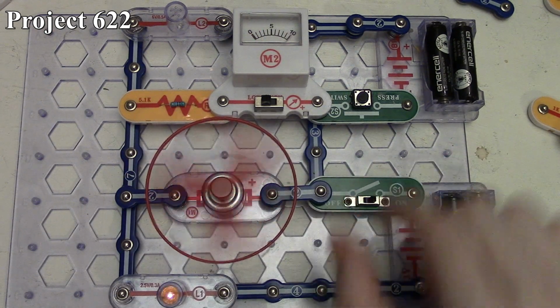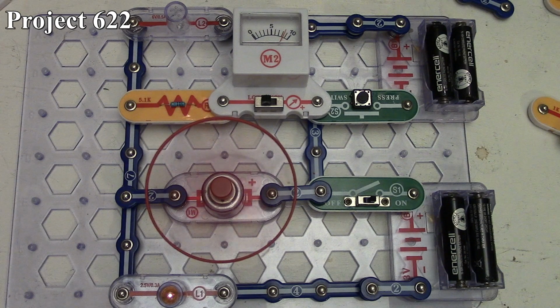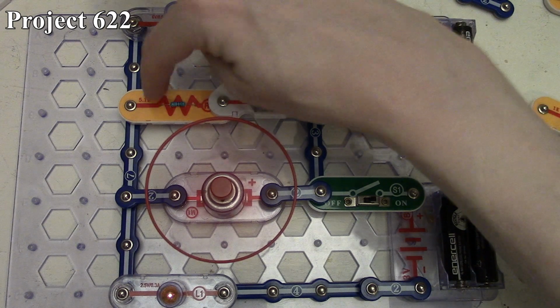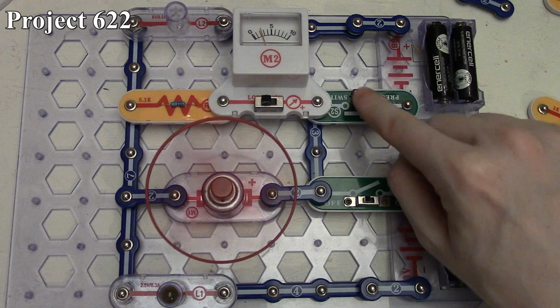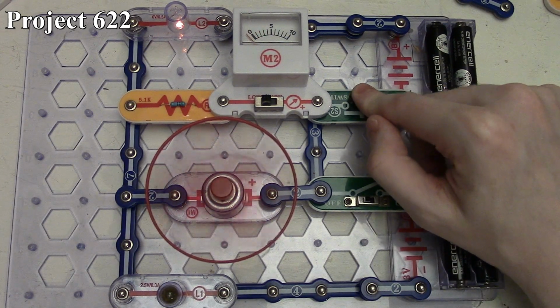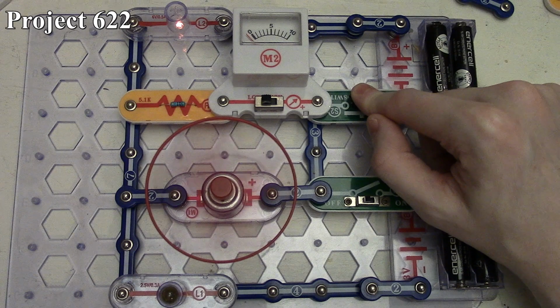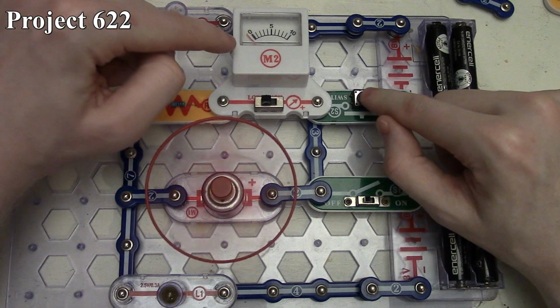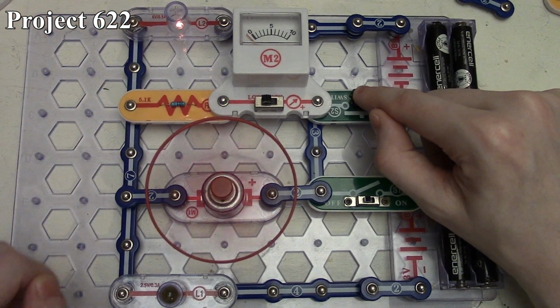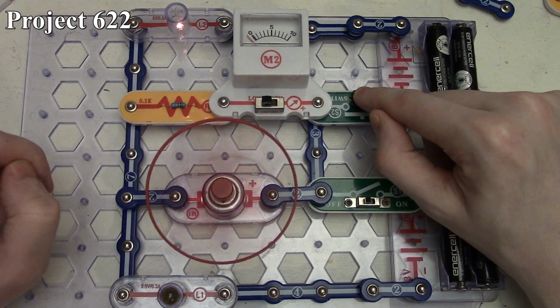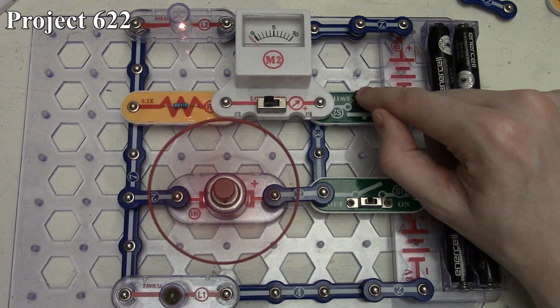So when we turn on the slide switch, our motor spins up in one direction and our 3-volt lamp there glows dimly because it's in series with the motor. And we can also see some current flowing through our meter, which is being limited by our 5.1K resistor. If I press the press switch, you see the motor starts turning in the other direction, and we actually have negative current on our meter there, because you see it's trying to deflect that way. And our 6-volt lamp glows dimly this time, because again it's still connected in series with our motor.